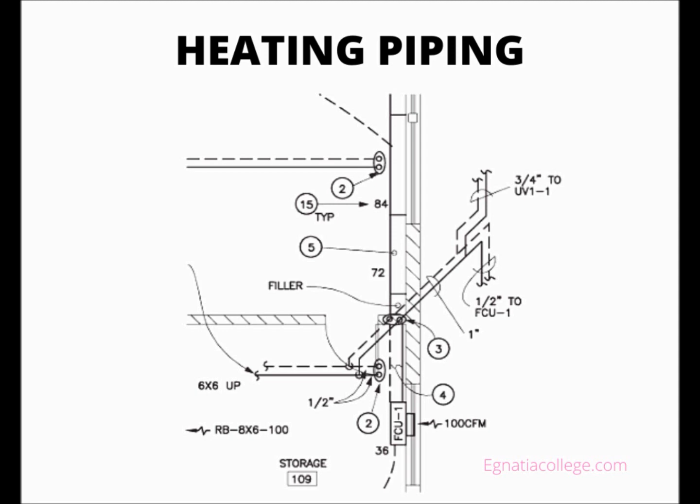Most of what is discussed here is also shown in this figure, but we will start closer to the center of the building, where the branch tees to the right, north, off the main supply running from top to bottom of the drawing. See the symbol legend A11 on sheet H1 to interpret the symbols as you trace the piping. It is recommended that you use a colored pencil to trace the piping as you read this.